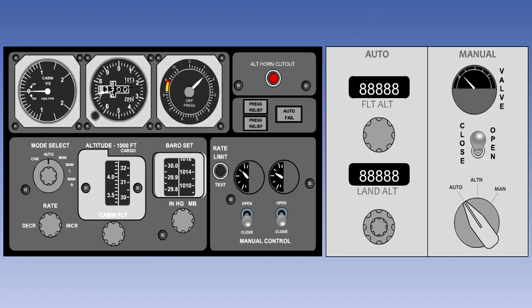Pressurization controllers vary in construction and operation. On simpler, small aircraft, they may be purely pneumatic in their operation. On old generation jets, they are electro-pneumatic, and in the case of most modern aircraft, they are electronically operated. Whatever type of controller is used, it will receive signals informing it of both the cabin and ambient pressures.